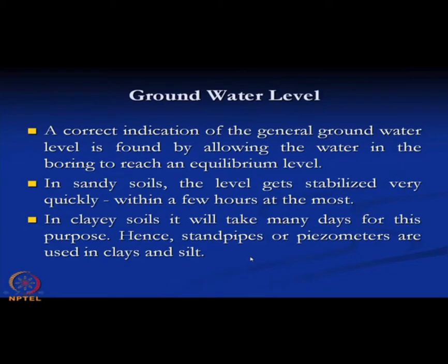So, the previous method is suitable for the sandy soil, because it takes very little time, say a few hours. But if it is a clay soil or silty soil, then it takes a very long time, say many days. So, that is why that method is not suitable for clay, and in that case the piezometer or standpipes are used to determine the location of the water table.